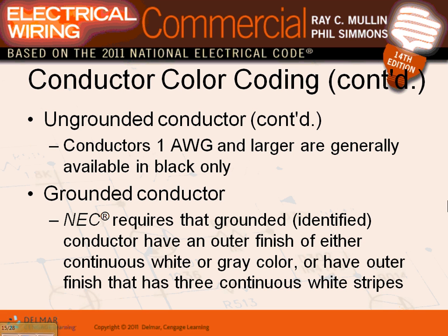Now the only thing you need to do is a few things. For the equivalent ground conductor, you either have to put a green tape around it, or you have to get rid of a couple of inches of insulation here, so that when I look at it, oh yeah, it's uninsulated, that's a ground. Most of the time they put a green tape around it. Now it becomes an equivalent ground conductor.